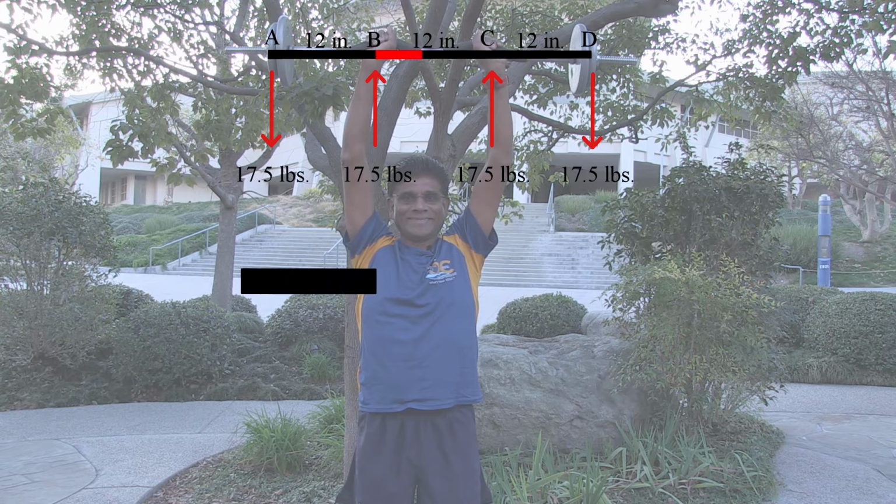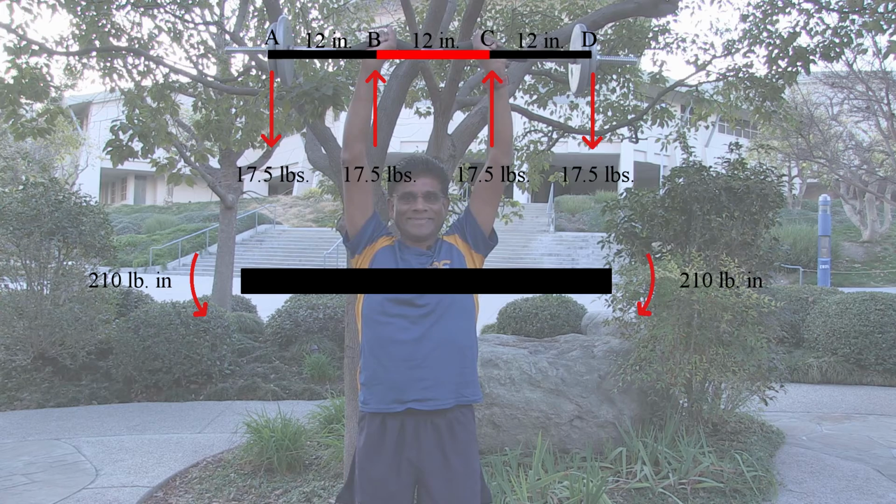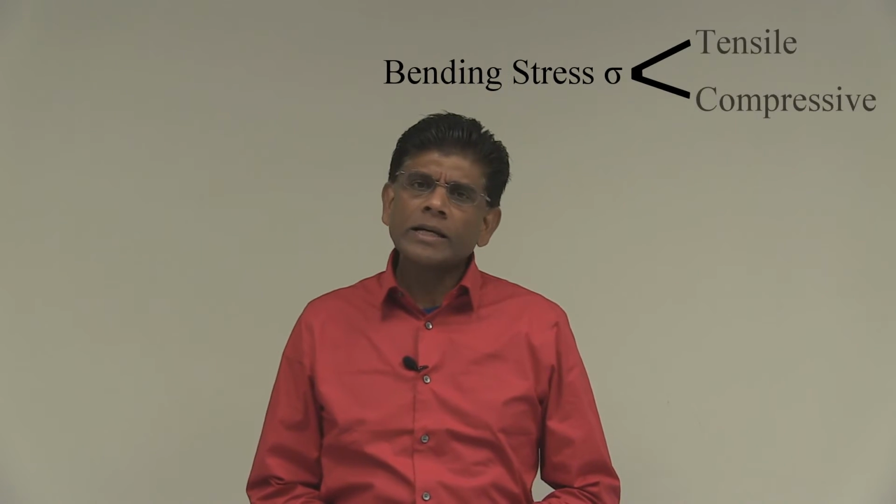Now let us draw the free body diagram of the center portion of the bar. The force of the weight and the reaction form a couple on each side. As you can see, this bar is in bending. Bending creates normal stresses. These normal stresses are tensile and compressive.